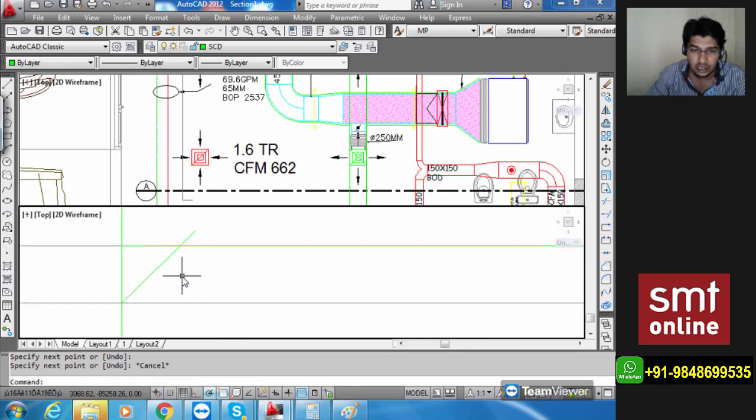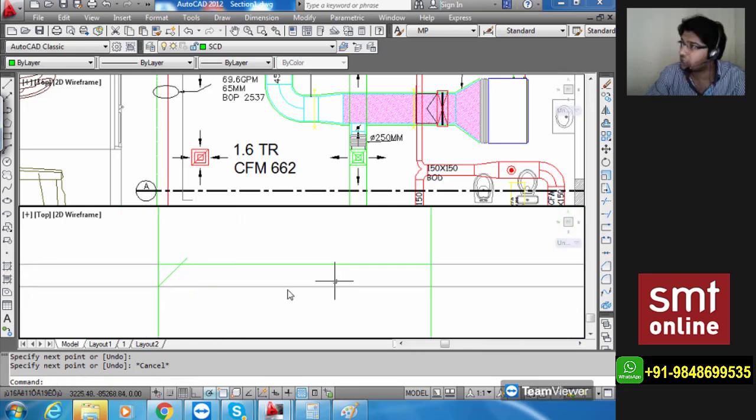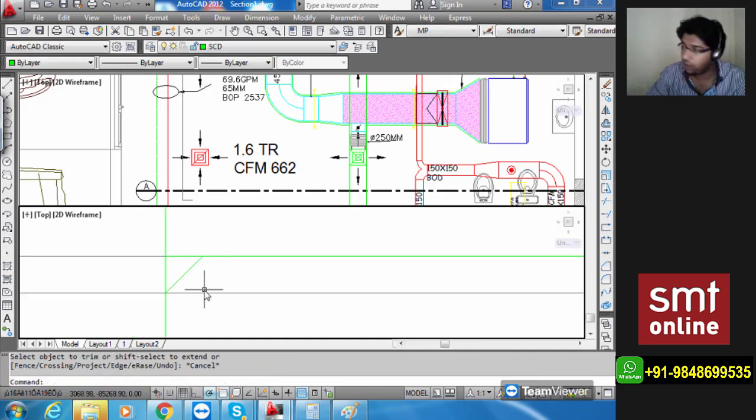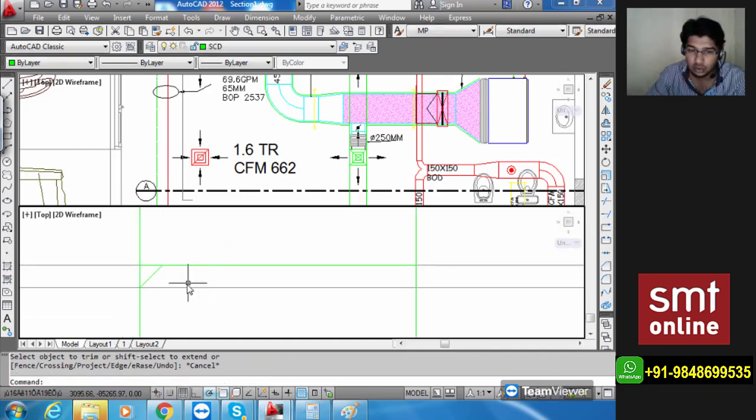Alright, there. So now I cannot use offset multiple times because offset is going to lie exactly in the line. It will come down. I have to copy that a number of times. So before copying, try to erase what is not required because that would be applied everywhere. How do we actually copy? You have to copy with some displacement values. That is a blade at every 1 inch.